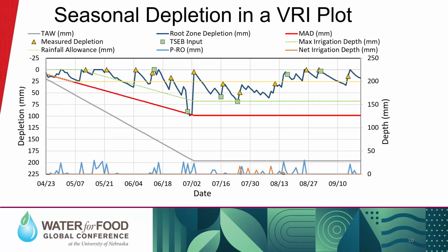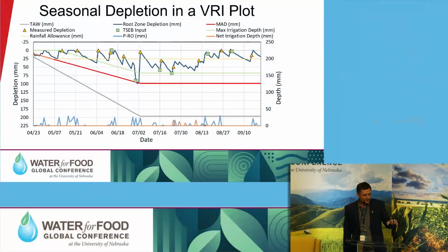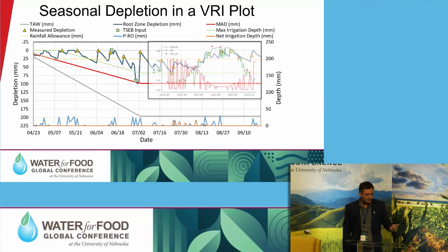That information comes from the soil probes, the soil moisture sensors, and when we use this ground data, we can calibrate and further improve the performance of the model. The green square is the evapotranspiration that comes from the surface energy balance model, which is combined with SETMI, the hybrid approach, to improve the model performance. And that's how SETMI works.